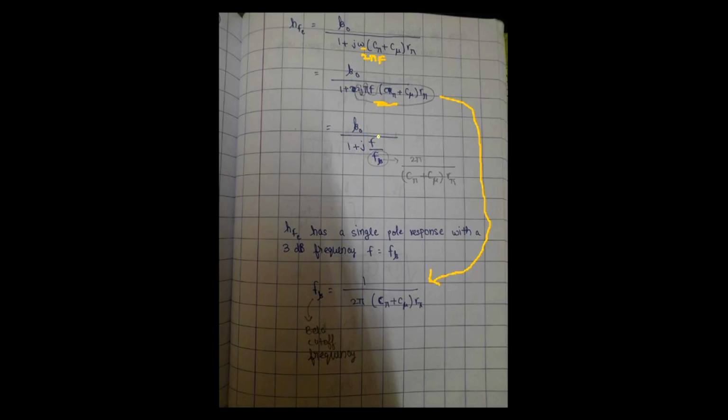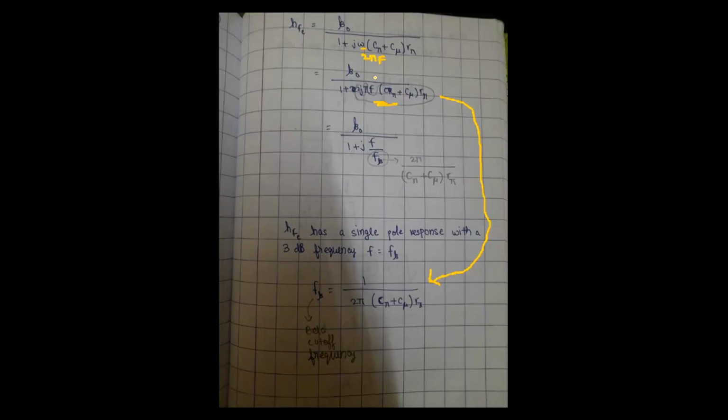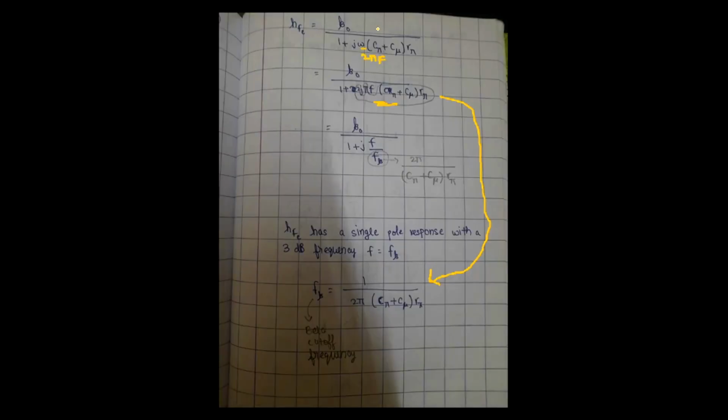So this tells us how much the current gain actually is, and to get the unity gain frequency, we have to take a very particular value of the frequency so that we get unity gain, which is where the current gain is 1. So for current gain to be 1, this entire expression has to be equal to 1.